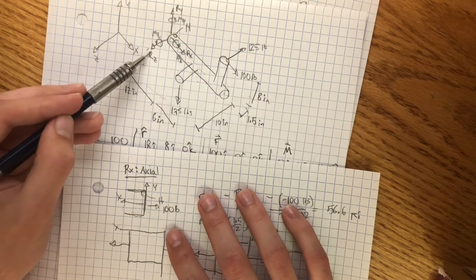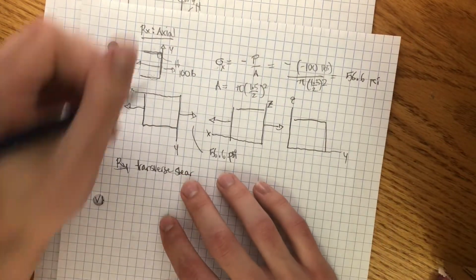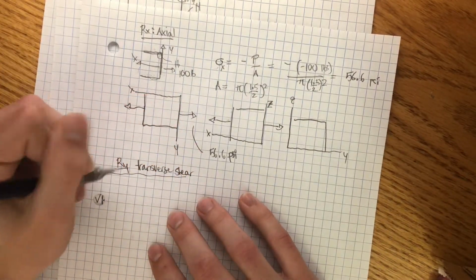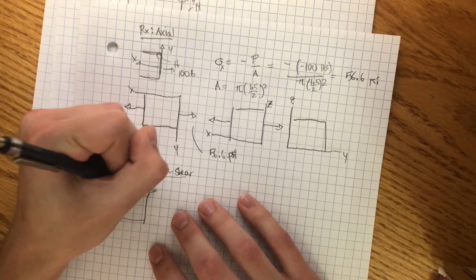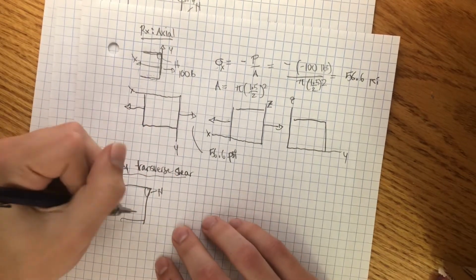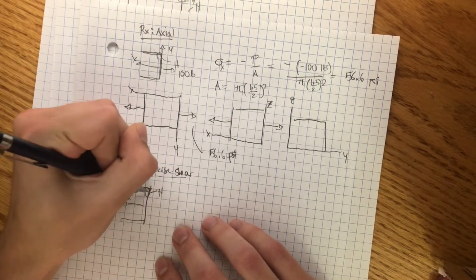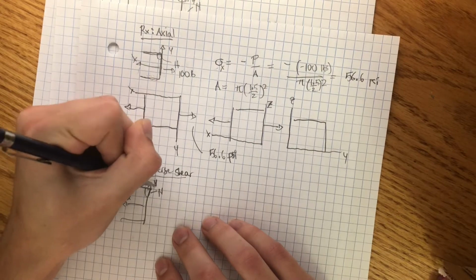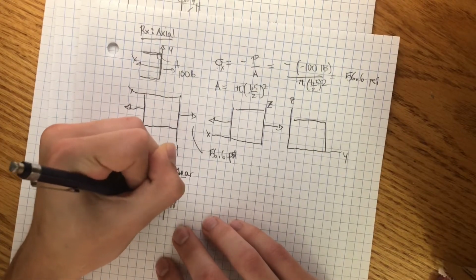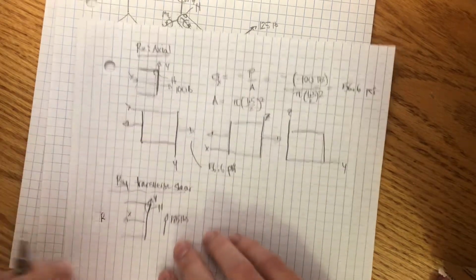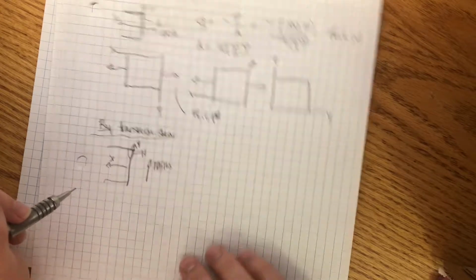With z coming out of the page. So we end up with basically the same little cross section as above here. We got h, and then got x, we got y, and then we also have our shear force, boom, 175 pounds, just going up along the y-axis right there.